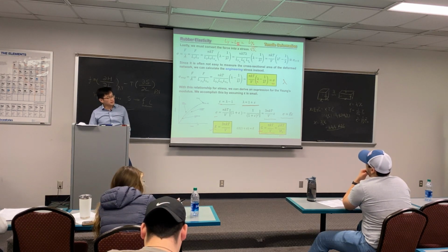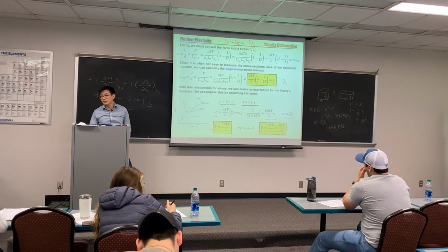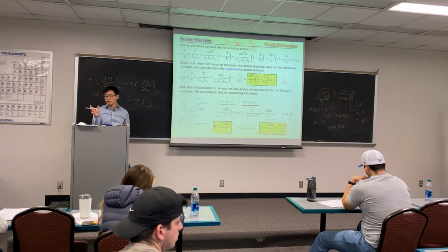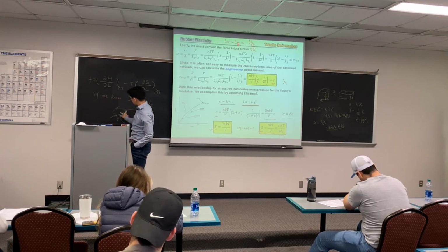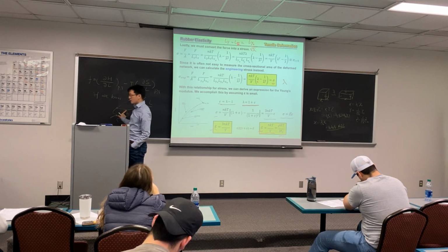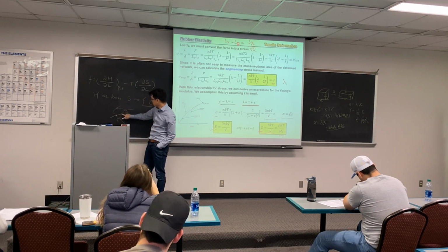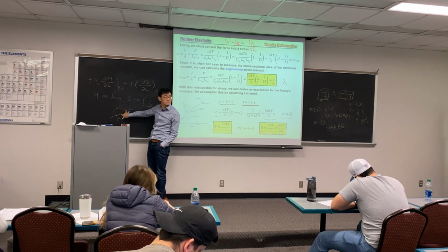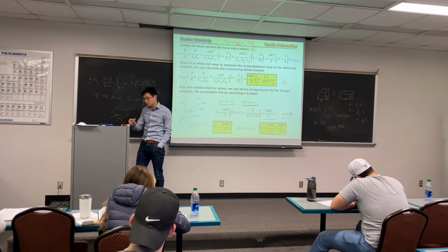It's telling you the same story. The more cross-link points n, or higher cross-link density, means that for the given network, the molecular weight between two cross-linked points will be lower. If you double the cross-link point density, meaning you add one more cross-link point there, your cross-link molecular weight is dropped by half. So essentially the same.